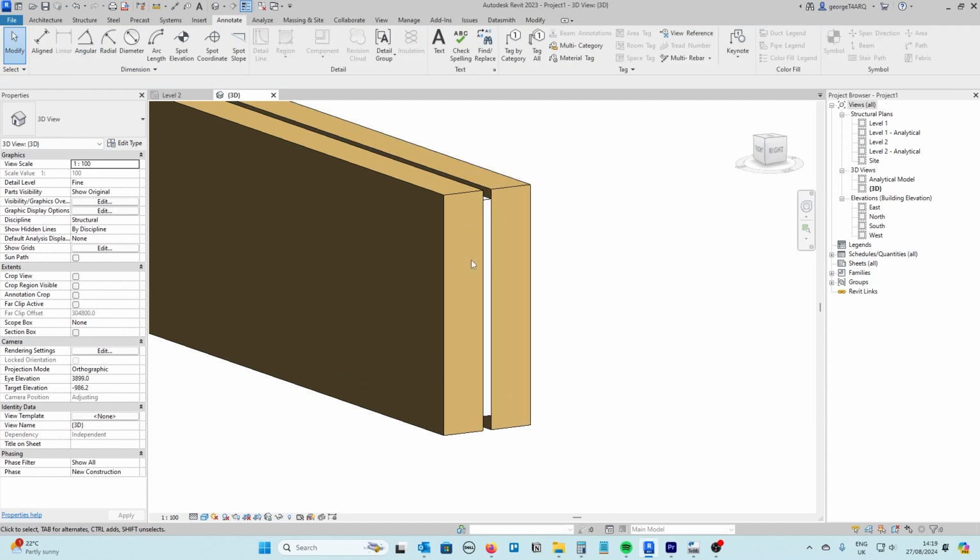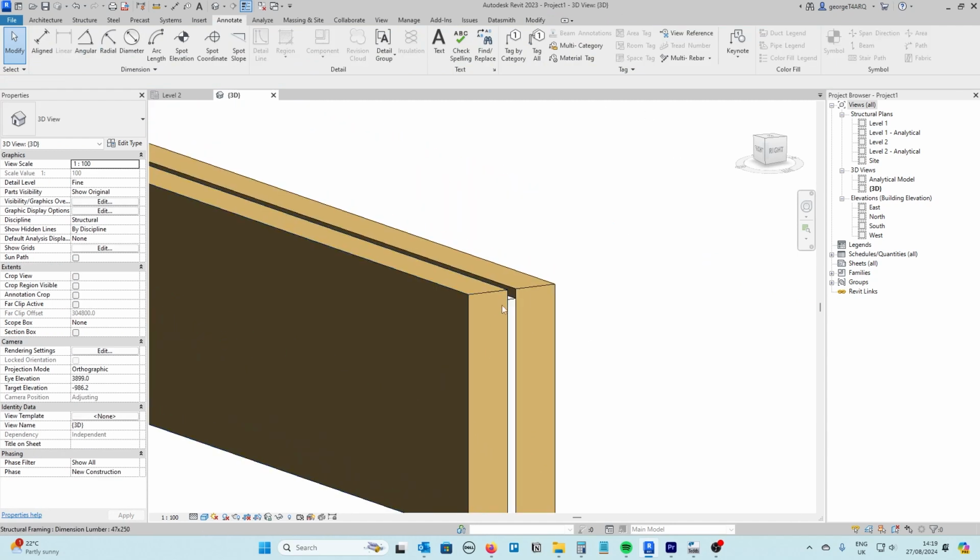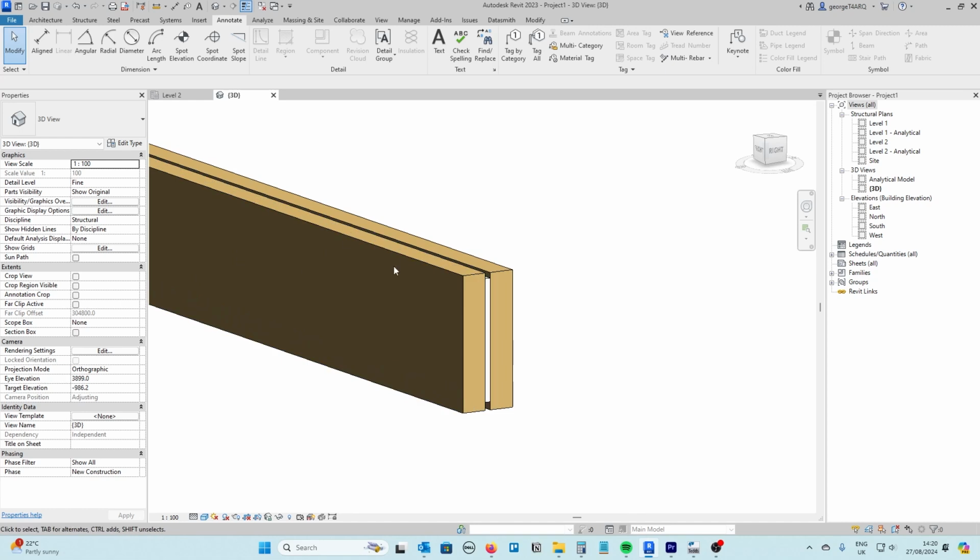The reason being, particularly if this was being used for flooring, if you had floorboards or joists over the top, you can imagine the timber is going to deflect, it's going to be compressed underneath the beams, but the steel won't be, and you don't want to end up with the timber sitting directly on the steel when the timber either side is then shrunk or compressed. So you keep this below it so that you never have that instance, and your timber to timber connection always remains the same.